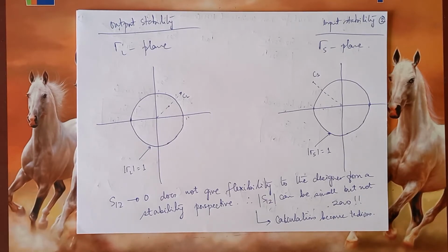If I have an MMIC with a non-zero S12, it is good for stability. But if I calculate the power gain or transducer gain of that MMIC considering S12 to be 0, even if it is not 0, how much error are we making in the gain?